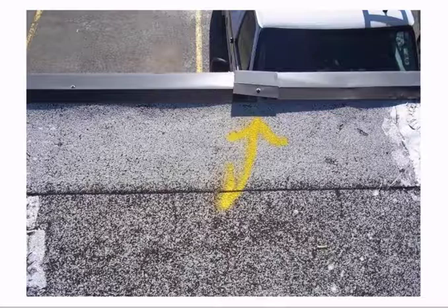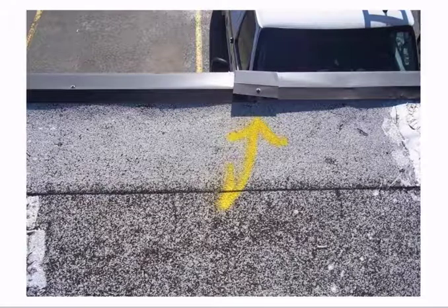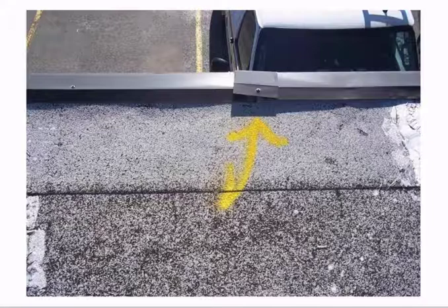Long term, you'd want that splice plate on the interior side of that, 6 to 8 inches long with a minimum of 3 to 4 inch overlap with your sealant in there, and it'll be better in the long term, more give and take on that sealant.